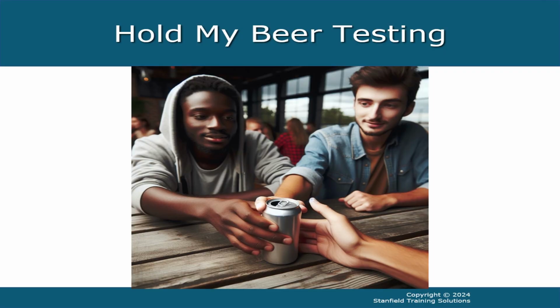There are many videos online showing techs trying to light A2L refrigerant, many of them failing. Note that the folks who could not get the refrigerant to light are flowing the refrigerant through an air-fuel torch. Because these torches are designed to aspirate enough air for more flammable gases like propane or acetylene, the torch design ensures that the mixture is well below the lower flammability limit by mixing in enough air to burn highly flammable gases.